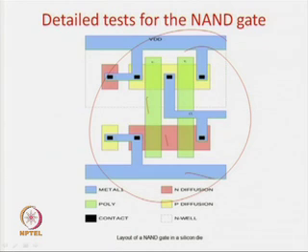Now, if I want to test this, things become much more complex, and the devices required are now something like an electron microscope, because I say that for the NAND gate this specification is, say, 0.5 micron. If it is much more than that, then I can say that it is not as per my specification. We can also say that the distance between these two metals should be, say, 0.7 micron, or some such specification.